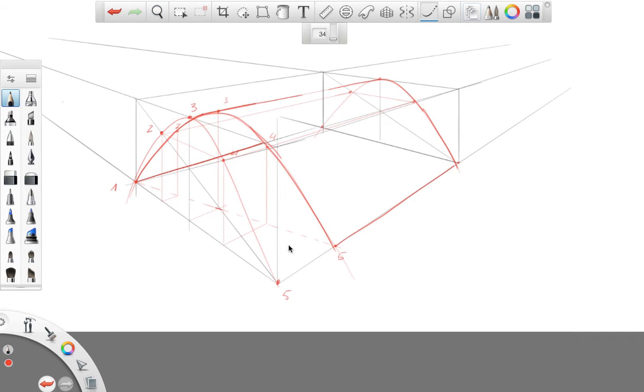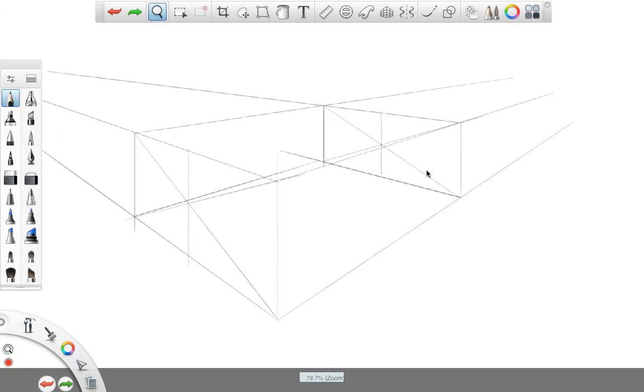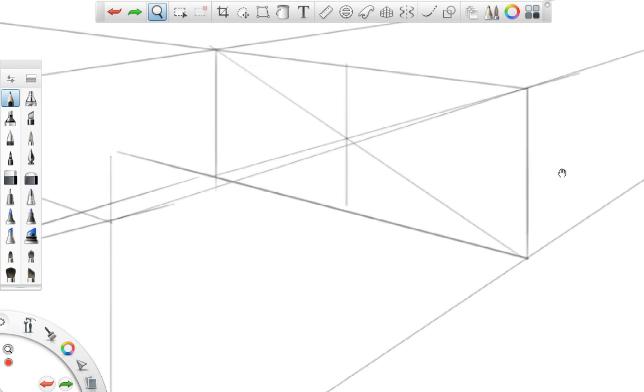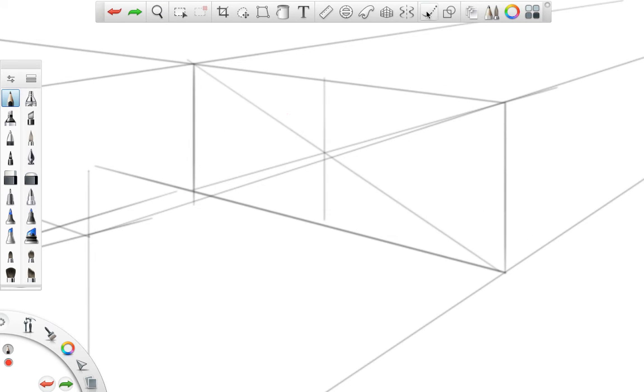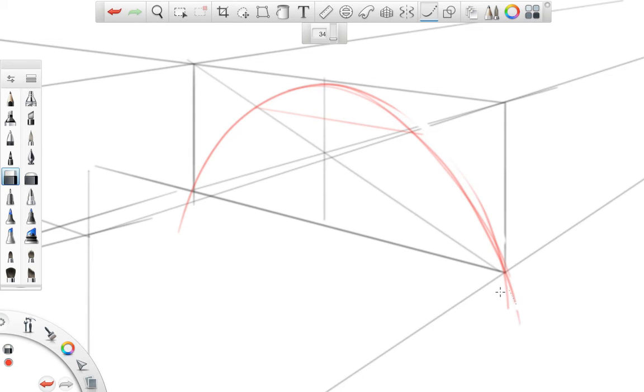Now we created kind of like a small tent, and then we cut one part out. So let's do a variation, and instead of this cut from the top, I would like to cut this through from the side. As good practice, in the back area this face is actually flatter than the front area, so it will be easier in this case to draw this arc on the back area first. I will plot this one down a little bit, maybe a little bit more upwards motion, a little bit more refinement. Yeah, maybe something like this. Okay, good. Let's double check the position for the cuts. So there it actually went up a little bit more. So maybe this comes there, and it should be maybe this way. Okay, good. And just clean this up a little bit. So it's just a quick underlay.